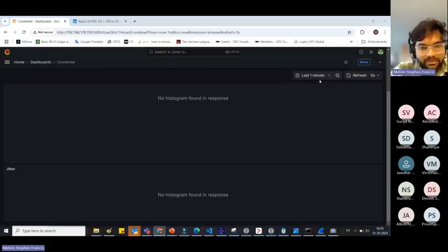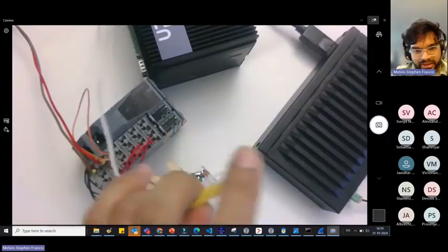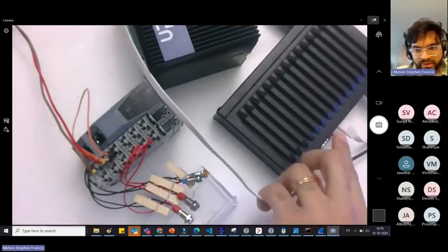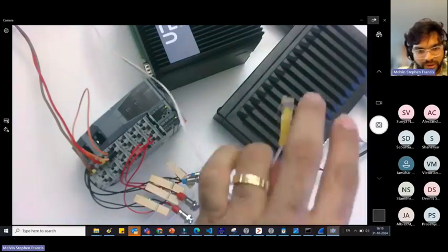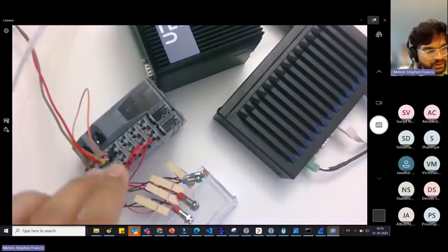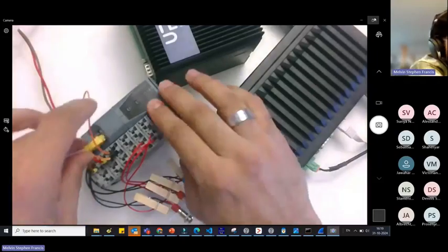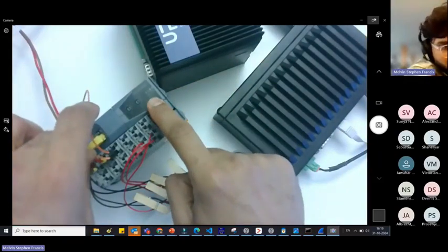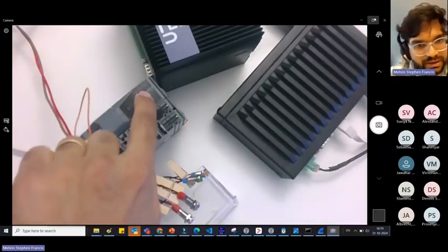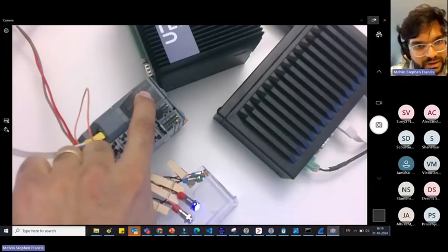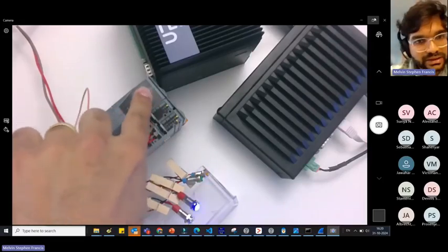And now I'm going to connect this particular Ethernet cable that comes from here. You can see this white flat cable. The same white flat cable from the TQ systems is going to be connected peer-to-peer to this particular B&R bus coupler, which runs OPC UA FX, and I'm going to connect it here. This particular LED that is blinking is the time synchronization. It has settled down, and it shows that it is in time sync.